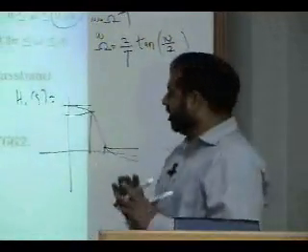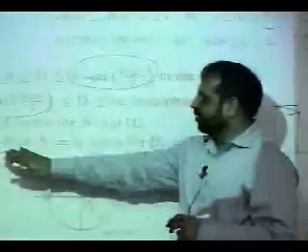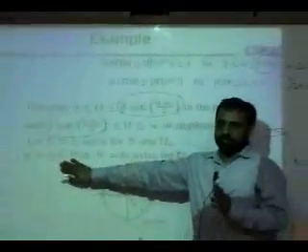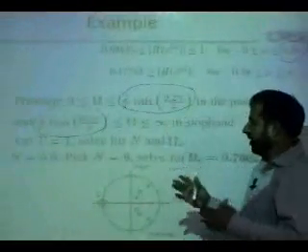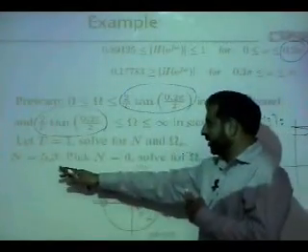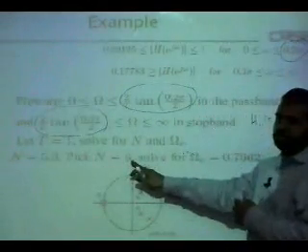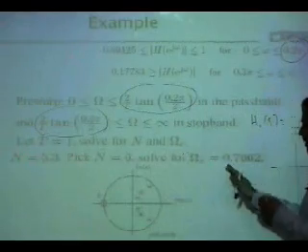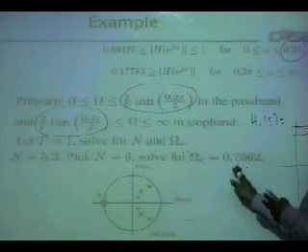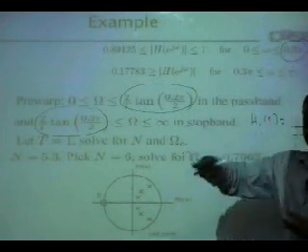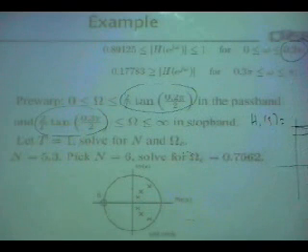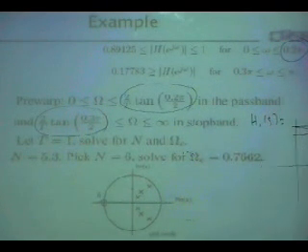The Butterworth design, still you find that it requires 5.3. Okay, it says 5.3, but whether it is 5, 5.1, 5.3, anything which is greater than 5 means 6. 6 means the same thing. Now omega c is this, so you design 6 poles and then find an H of s and take that H of s to H of z.